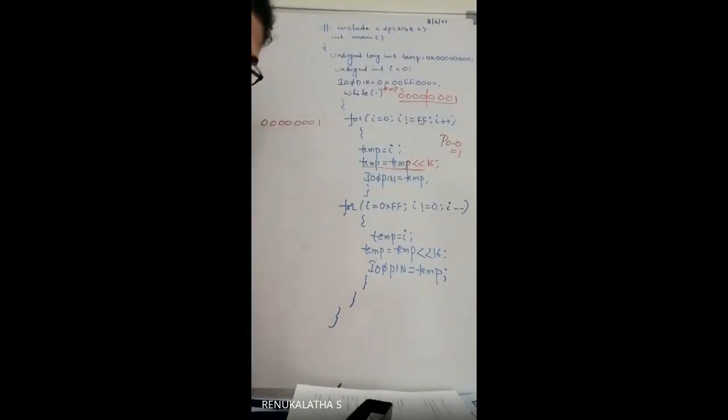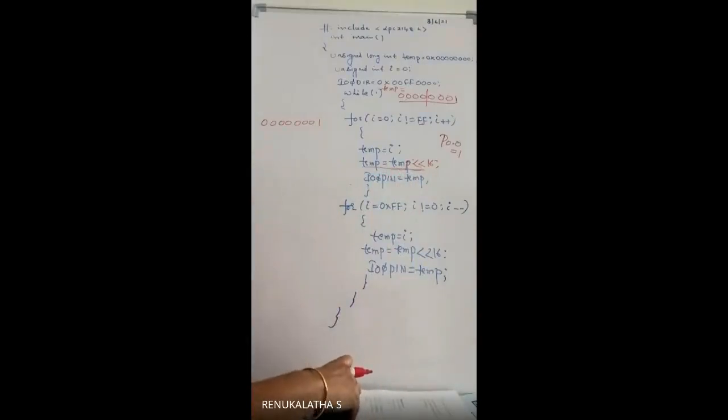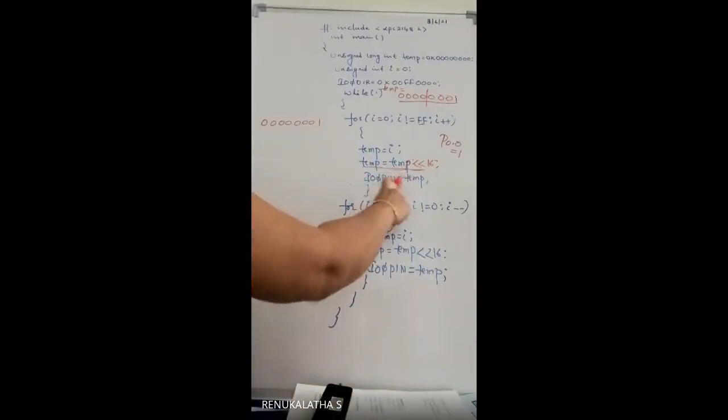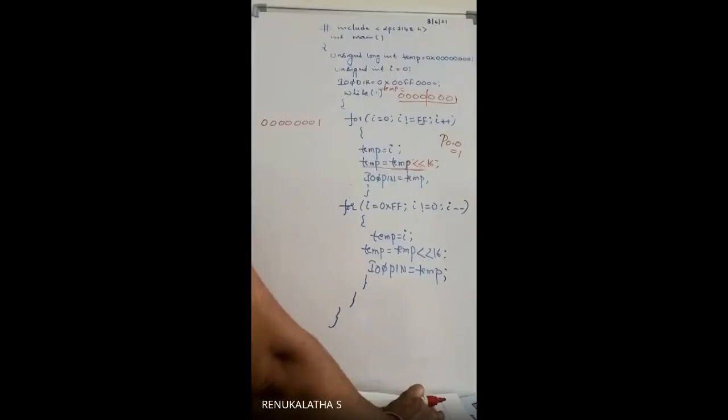the DAC. No, before that. When you place this value into the IO0 pin register, the data will go to where? Port 0. Okay, which pins? 16 to 23. Those pins 16 to 23 are connected to the data pins of the DAC. Then the DAC will receive the information.